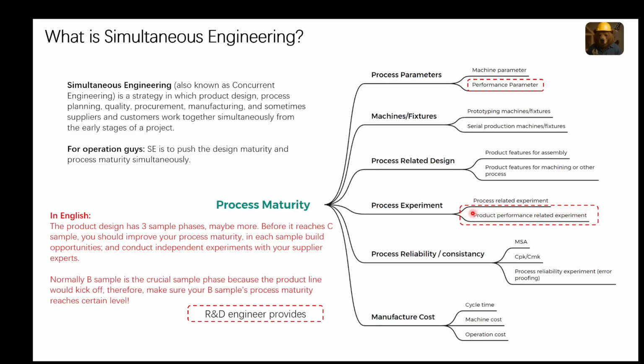For example, you choose the gluing process here. If the product should go through 300 cycles of thermal shock, how many rounds of thermal shocks it should withstand is the bottom line, and your R&D guys should define this. Then you can say, okay, I chose the gluing process here to make sure part A and part B can withstand all these thermal shocks. Or you can say gluing process is not okay, I will switch it to soldering.